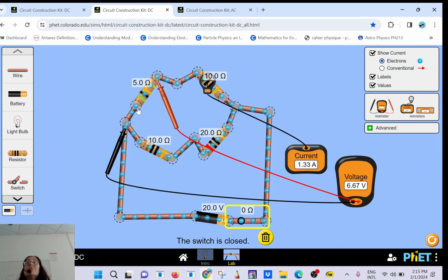Now I can use Ohm's law. You have a resistance here, it's 8 ohm. What's going to be the current? If I use the RMS voltage, I will get the RMS current. That's going to be 3, you sure, right? Yes. 3 what? 3 amps. And the current is going to flow one direction, the other direction, one direction, the other direction.